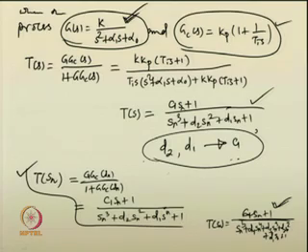We may get a transfer function which will give us the desired time response of a closed loop system. That is the objective. Then from back calculation, since d2 and d1 are made up of the coefficients or parameters of the controller, one can easily estimate the controller parameters.